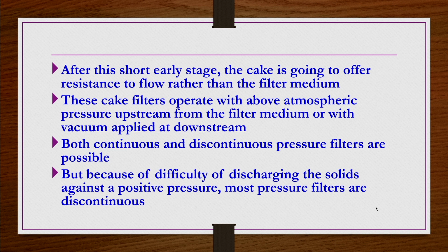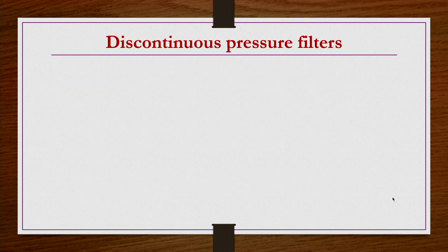But removing such solids or cake that has formed on the solid surface against a positive pressure that has been provided for the filtration to occur is a very difficult task. Because of that, most of the pressure filters are discontinuous filters, though it is possible to do a continuous filtration process also. So, because of the difficulty of discharging the solids against a positive pressure, most pressure filters are discontinuous rather than continuous. So, let us start with discontinuous pressure filters.